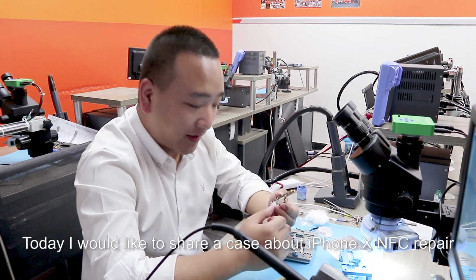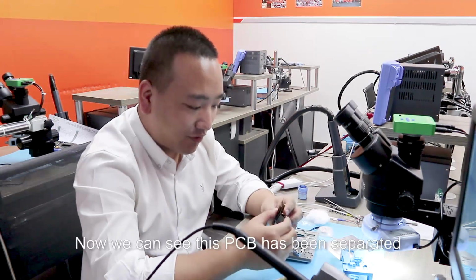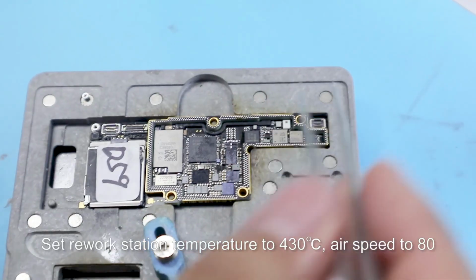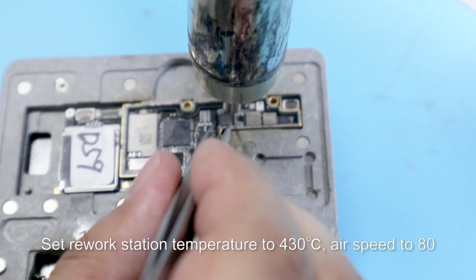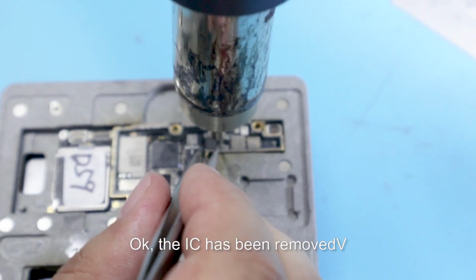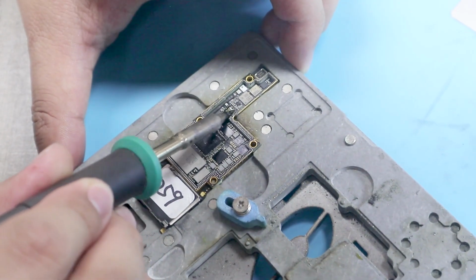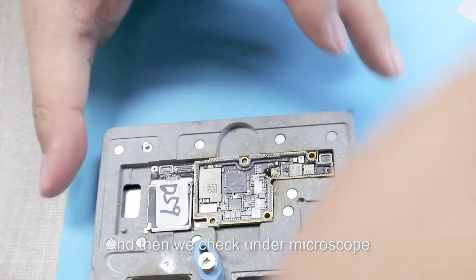Hello everybody. Today I would like to share a case about iPhone X NFC repair. Now we can see this PCB has been separated. Then we need to take out this IC. Set hot air station temperature to 430 degrees, airspeed to 80. Okay, the IC has been removed. Let's clean the pad. And then we check under microscope.